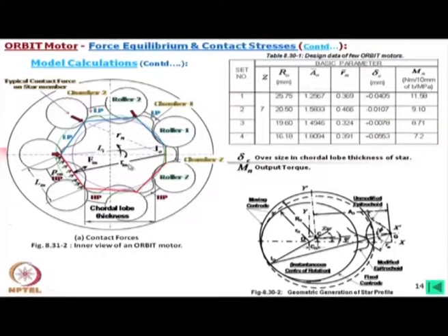For an ideal case, whatever the distance is, we consider it the ideal dimension. Now, if we increase these dimensions by this much only, which is the practical case we have taken, then certainly this is an interference fit, and for such a machine this is the amount of torque we can get out of it.